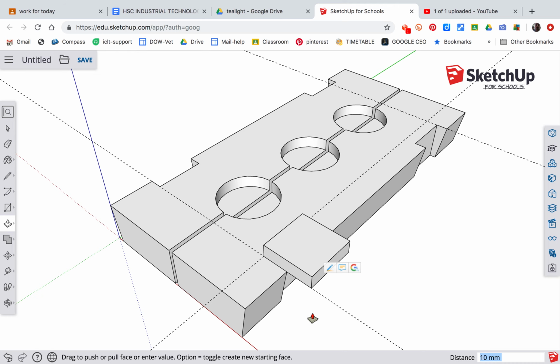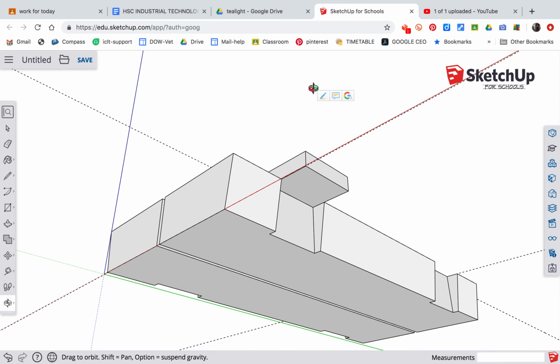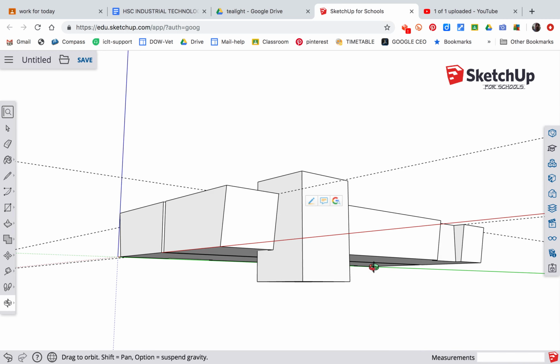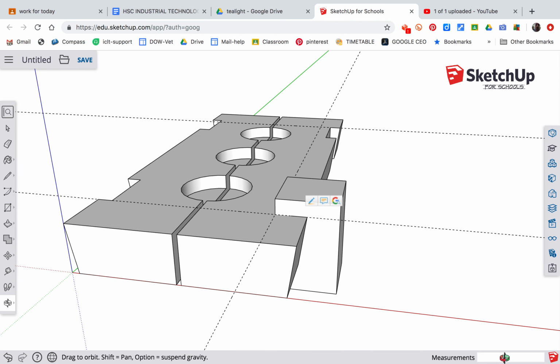And we're going to use O to orbit round to the bottom now, and we're going to pull it down from the bottom here, another 50 millimeters. Okay, so you can see it goes through, but what you probably realize now is that it actually intersects this object, and we could tell that if we go to over here.